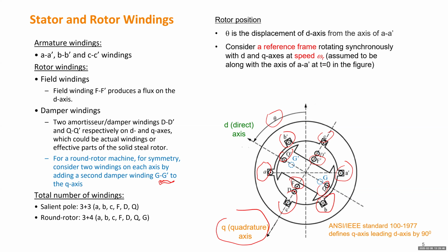So that means when we study the stability of synchronous generators, we only care about the angle of each generator relative to some reference frame. That reference frame can be the rotor of one generator, or could be some common reference, like the average position of all the rotors. So it's more convenient if we just define a reference frame. This reference frame is like some fictitious generator that will never lose stability. It always operates at perfectly 60 Hertz. Then we can compare the rotor position of this generator versus that fictitious generator, that reference frame.